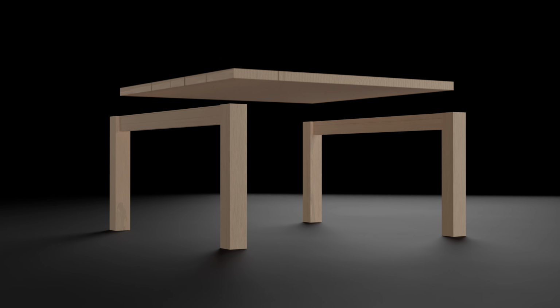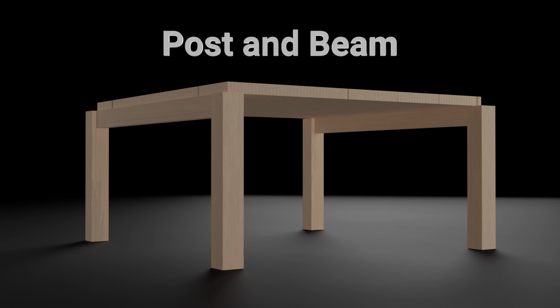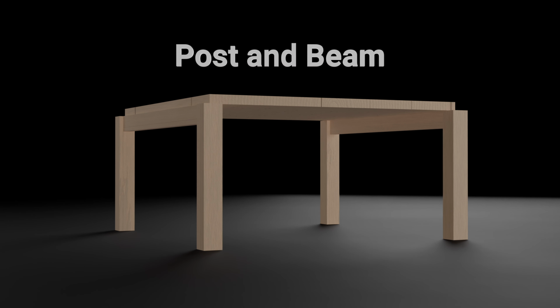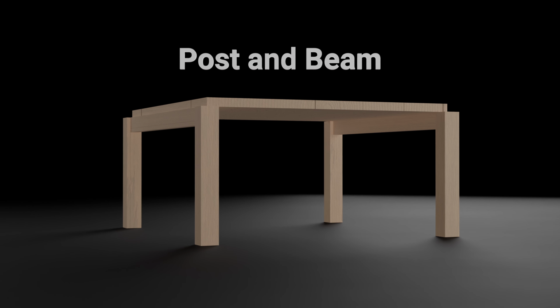Next up is the post and beam system. The post and beam system uses large wooden columns and beams to form a strong structure. This method is ideal for open floor plans because the beams carry the load of the upper floors and roof, eliminating the need for internal load-bearing walls. Because of this, internal walls can only be used for dividing spaces, instead of supporting the building.